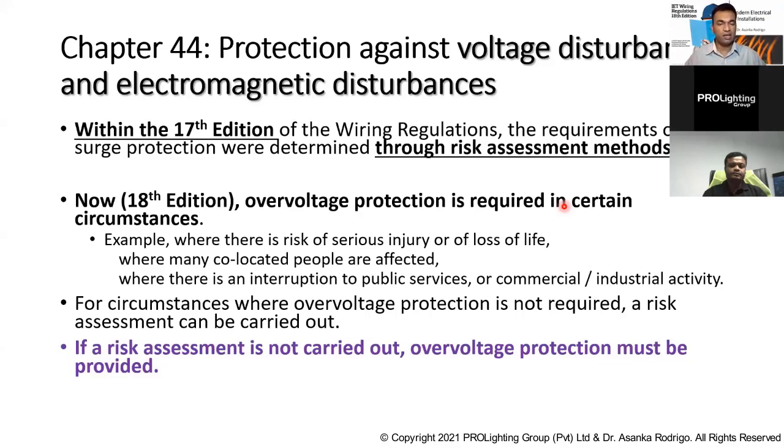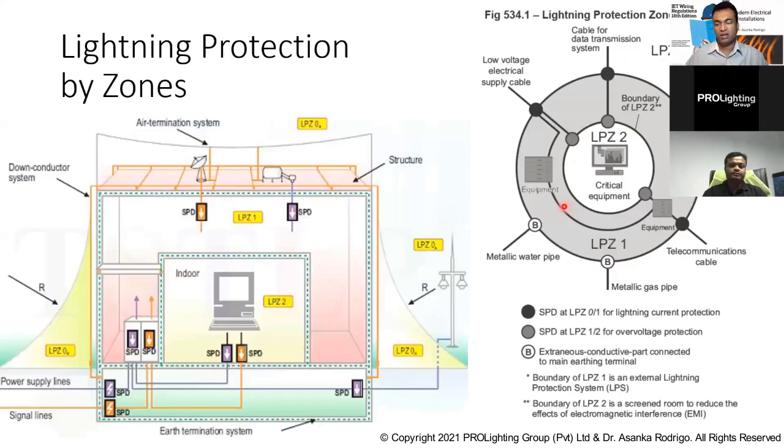so that when we are designing our electrical system, we cannot follow the earlier traditional type of distribution system, assuming that we only get 50 hertz, the power frequency waveform. Now our system is more distorted, and we are getting a lot of high frequency components, so we have to take those things into account when we are designing. I will quickly go through them because we have limited time.